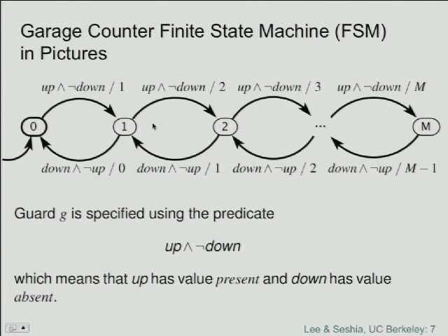Yeah, question? The empty graph would be the zero or the absent. Would be the zero or absent state, or absent output. I'm saying that you still have natural numbers, so there is still zero. Yes, that's true. But notice there's potentially another flaw in this design, right? When is the output 0 produced? It's only produced when the last car leaves. So when you initialize this system, you do not, in fact, produce the output 0. So if you're using this to drive a display, the display will not show 0 when you boot this thing up. Okay, potentially another defect in the design.